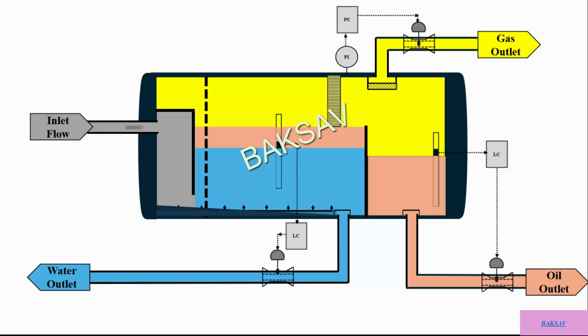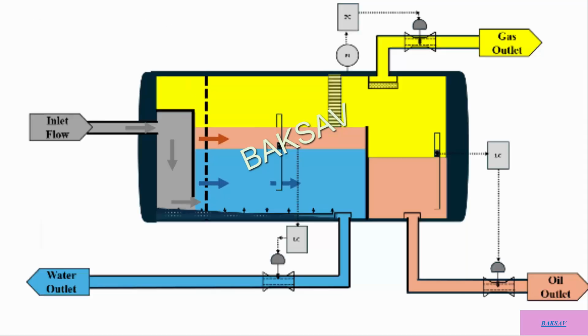Oil-water-gas flow enters the separator and passes through a diverter that prevents splashing of the entering flow over the main separator section. Then the liquid flow passes wave breakers or baffles and is stabilized, which allows more efficient oil-water separation to take place. Separated water is accumulated at the lower level of the vessel.